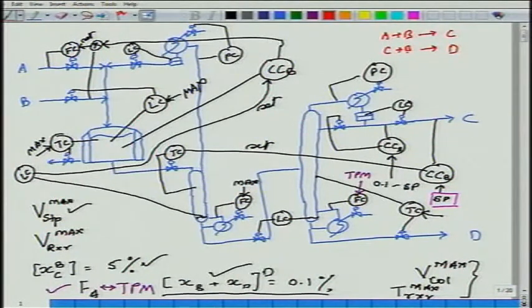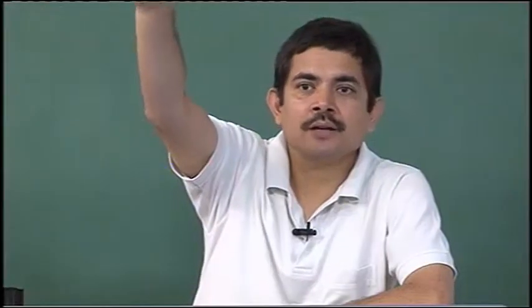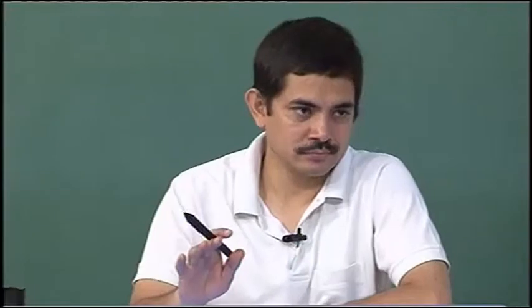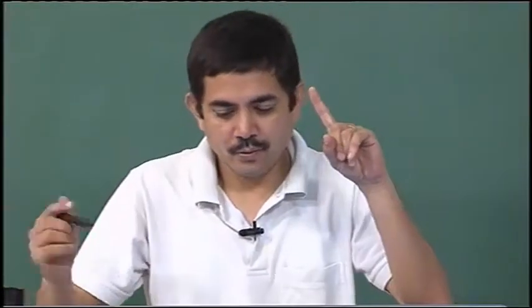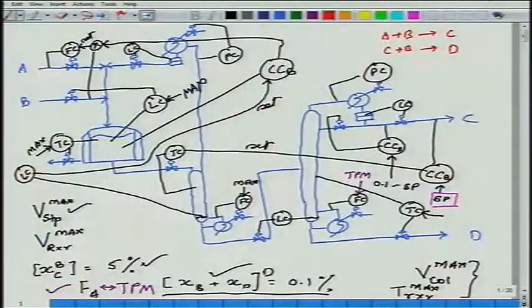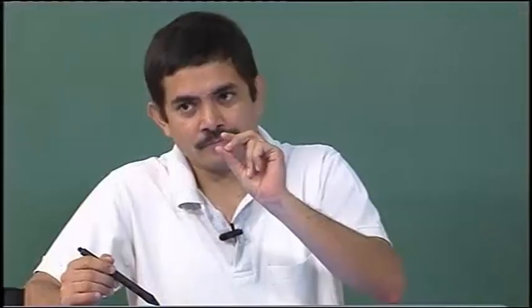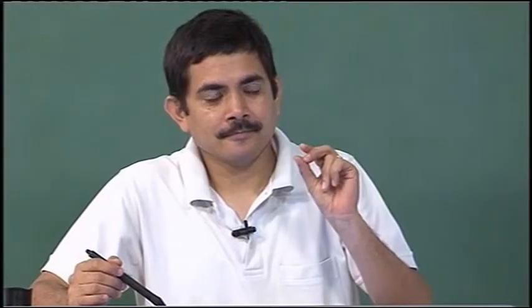Let us say 0.1 kilomole per hour D is going up the top. In another system that 0.1 is actually 0.01 because you are allowing benzene to leak out. In 1 mole of D there is already 1 mole of A and there are 2 moles of B, right. That means my raw material consumption of B goes up by whatever that small extra amount may be. Yes or no? I don't want that.